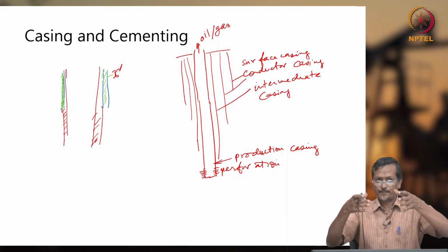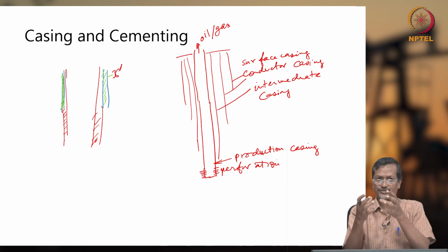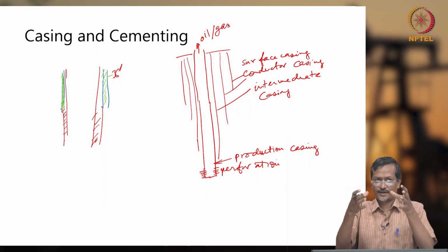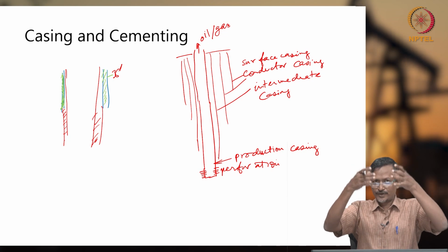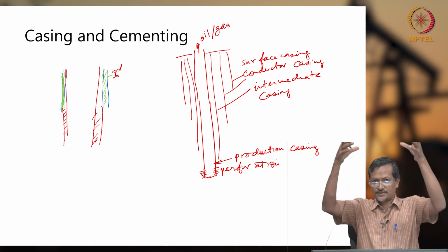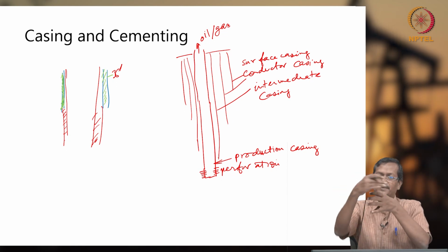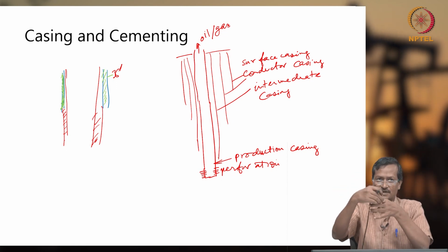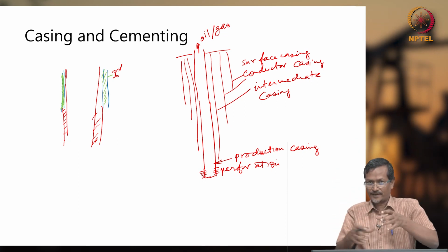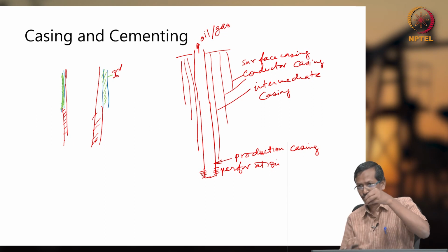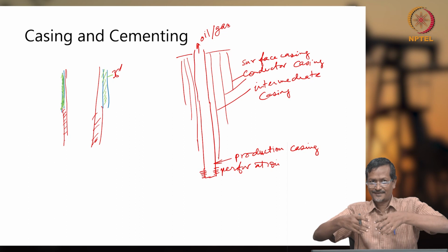So you drill a hole, you put a metal pipe, then you inject a very high pressure cement mixture. You create a cement slurry, mix it and pump it at very high pressure. When you're pumping, it will fill all the gaps in between the mud and the pipe. When the gap is filled all around, you give some time for settling. Once settling is done, again you put another pipe, drill pipe, and start drilling. Drill further, maybe 100-200 feet. Then again you put mud, again cement it.